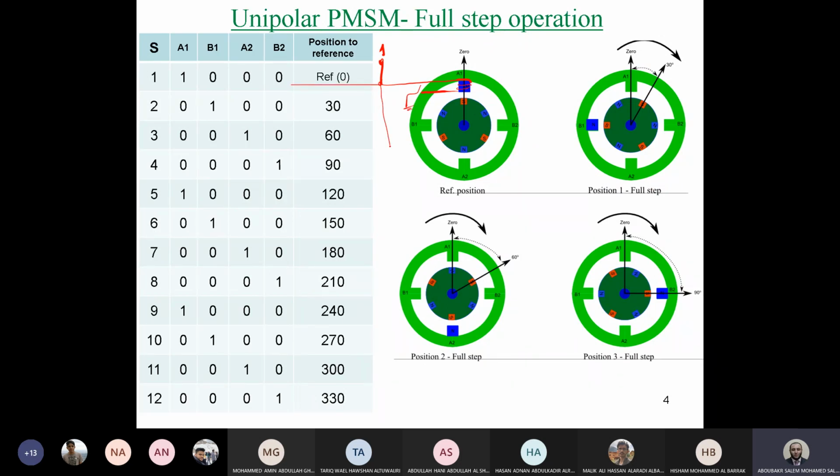And the other half of the coil is connected to the other tooth and through a switch to ground as well. So if we energize half coil A1, this means we are going to turn on this switch, and the others will be open circuit. So this is the sequence of pulse configuration here. 1A is active high, and the others are 0. And let's assume the first operation or first step as reference, like what we made previously.